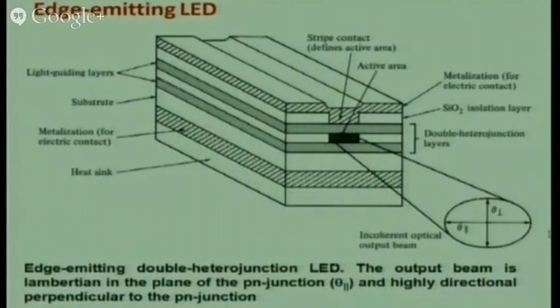So if I minimize the dimension of the cavity, I restrict to narrow bandwidths, right? Basically I can restrict the wavelength which is coming out. The output which is coming from the edges is again Lambertian. It gets emitted in this direction as well as in the other direction. So it carries a wavelength pattern like this, right? Both dimensions are possible. So the concept is the same.